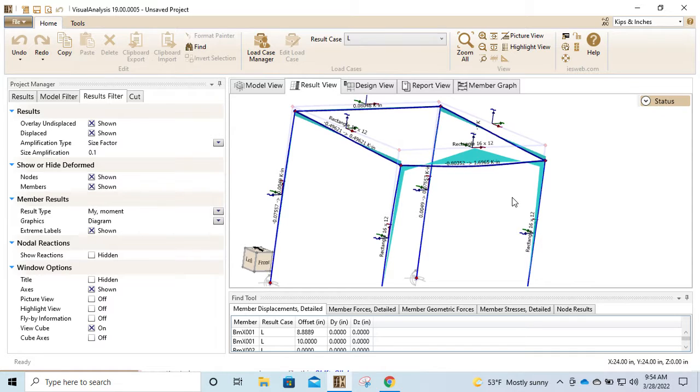We've got a point load at a distance m. That point load will give you a magnitude of 8 kips, so it's acting in that direction. The moment I give you a magnitude of -175, what does that mean? Well, that means it's acting in the opposite direction of what's there. I drew this, copied it, and then I wanted it to go the other direction. So just know that that moment should be applied in the other direction.